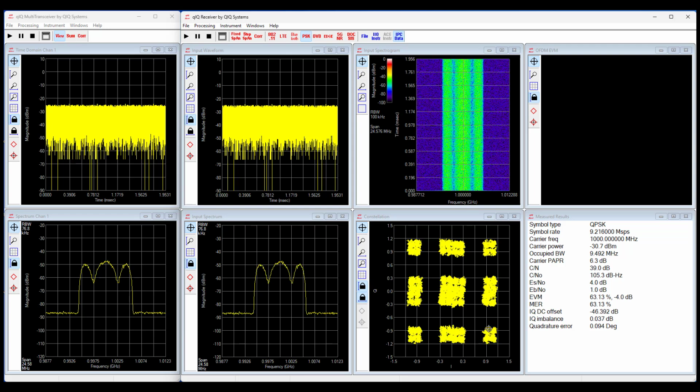And you'll notice now that there's a lot of error in here. It's still QPSK, the symbol should be here, but now it's a big QPSK on QPSK with yet another under. Anyway, it gets to be very complex at this point. The demod would not be processing any signal of use at this point. The bit errors would be way too large.